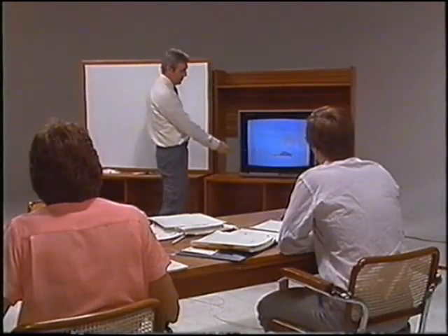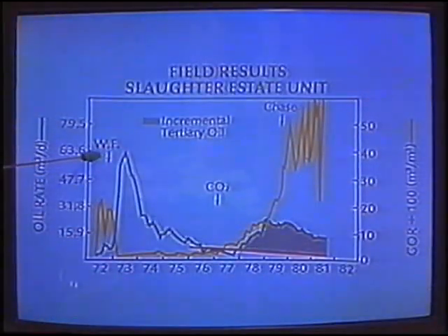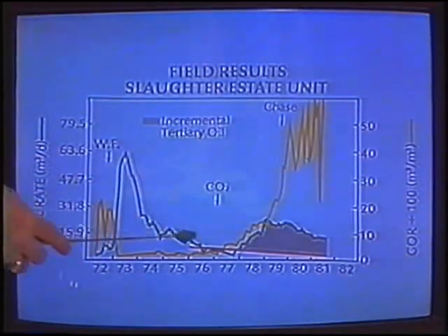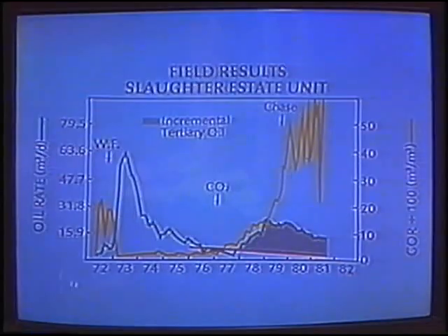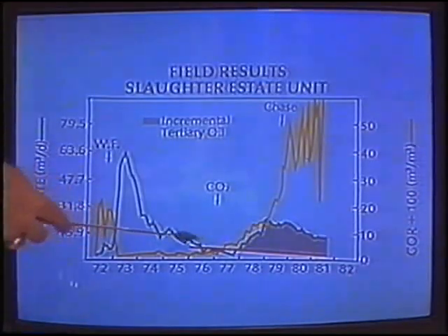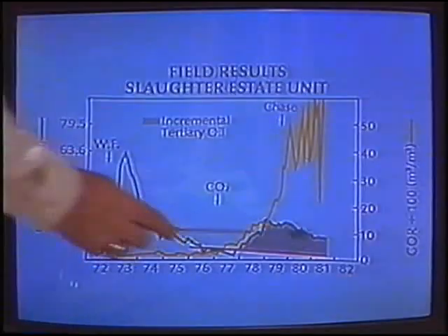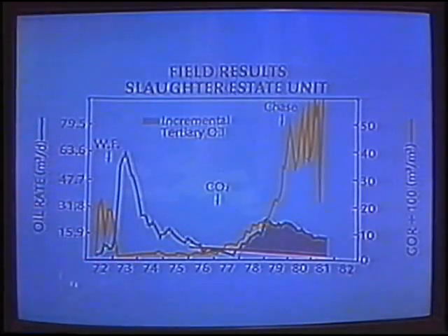So before they did anything, they began a water flood in the project, and you can see the response in the oil rate to the water flood. Water flood did pretty well. Okay? And then after that, they followed it with CO2, but they did not jump the gun on it. They waited until there was a well-established decline to the water flood such that they could extrapolate it, and then they put in the CO2.